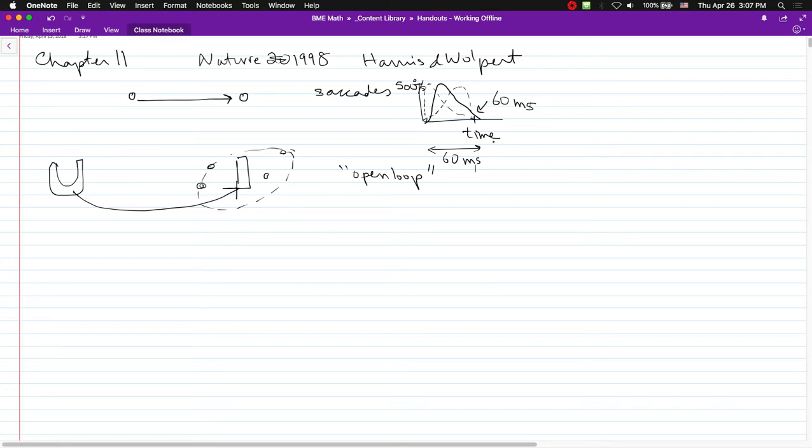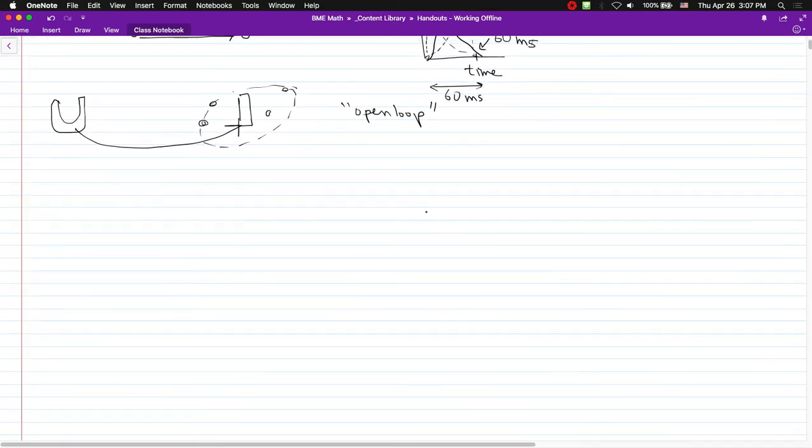All right, so let's do it so you can see how to do it. Okay, so you have some dynamical system, and you have m x double dot plus b x dot plus k x is equal to some force. So you have something that you're going to move, and that force is going to tell you how you're going to move it, and it depends on its position, velocity, and acceleration. And so therefore, acceleration is 1 over m times force minus b x dot minus k x. All right. So how's force related to the commands you send?